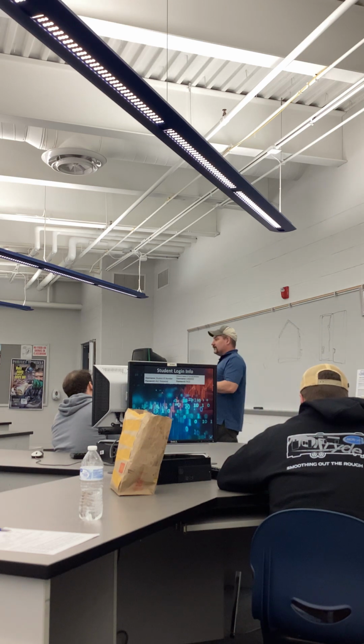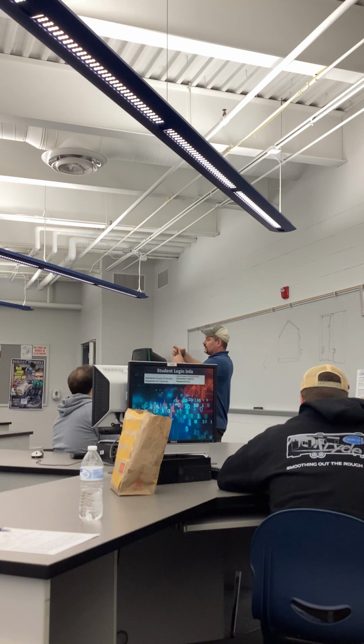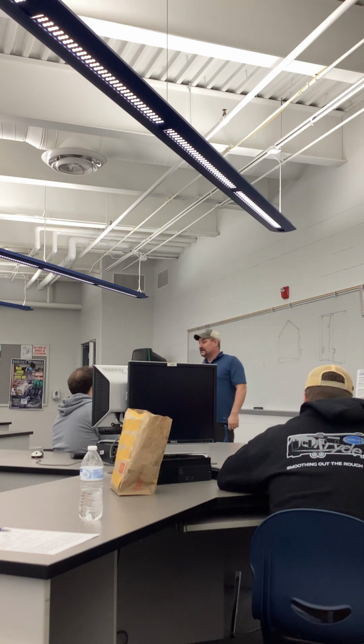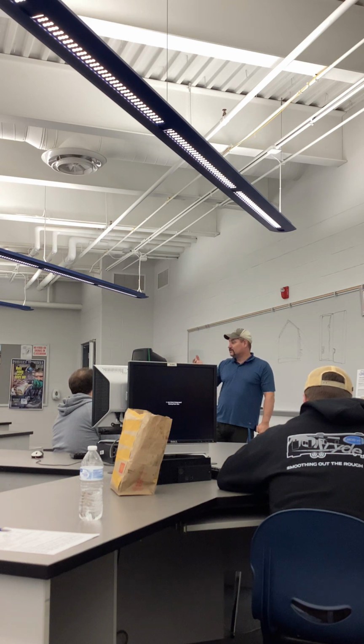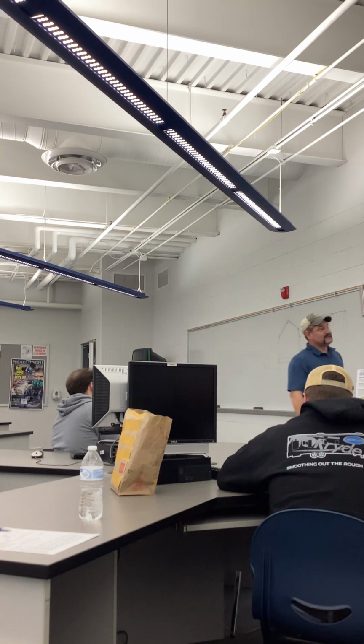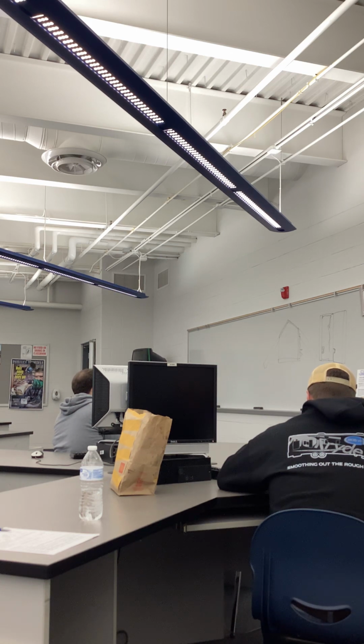Drill a hole for a wire, if one wire goes through, you've got a 2-inch hole, and now you have air leaving your house through that 2-inch hole constantly. And it is constant. It never stops. When it's cold, when it's hot, it never stops. So you have to foam those openings and seal up all of those areas for your house to be what you would consider efficient. There's always too much, but on the same hand, we are so far from too much most of the time that we could do a lot more.